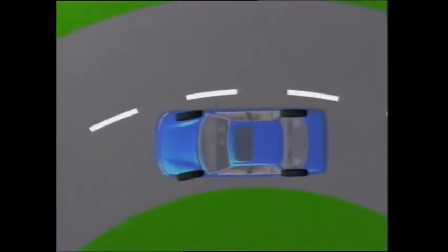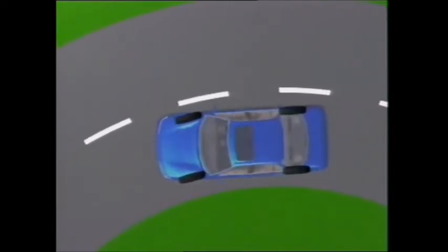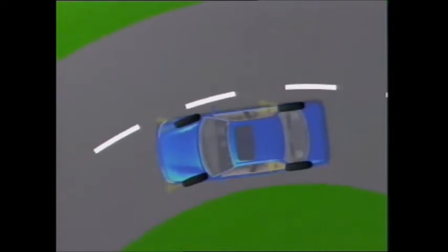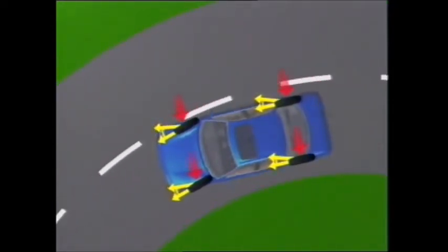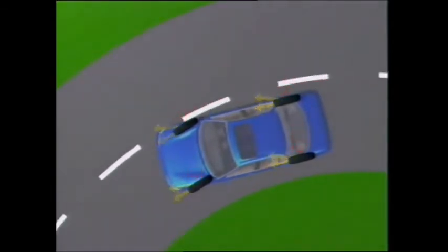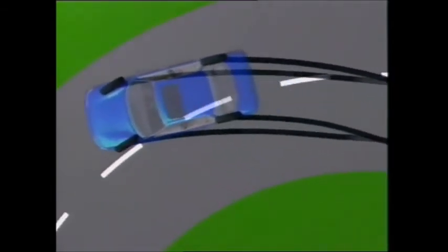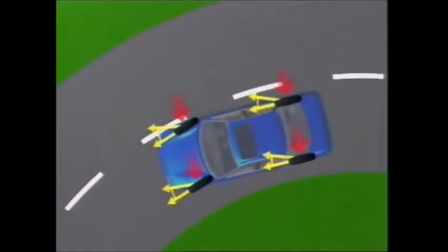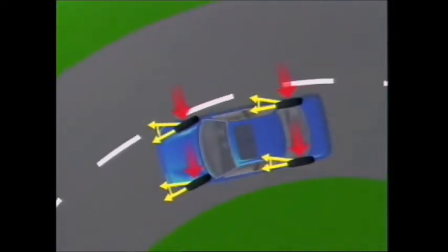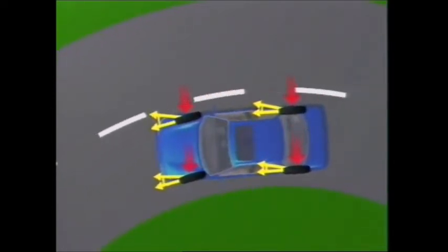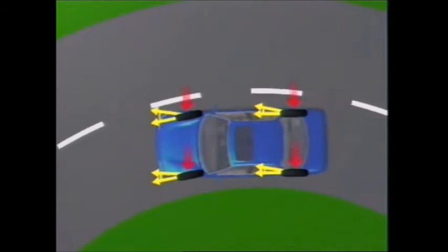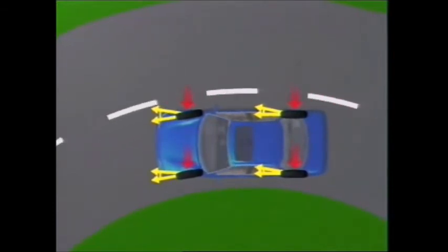This vehicle is being driven into a turn with decreasing radius. Both slip angle and cornering force increase until a point is reached where the tyre slides, and the only resistance comes from sliding friction across the road surface. The tyre grips again only when the vehicle has slowed or is making a turn with a larger radius. That is, when the side force is reduced to a level the tyre can withstand without skidding.